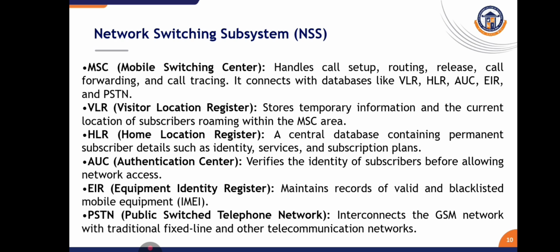The VLR is a database which contains the exact location of all mobile subscribers, and the HLR is a database containing data pertaining to subscribers authorized to use the GSM network. The authentication center authenticates the mobile subscriber that wants to connect to the network.